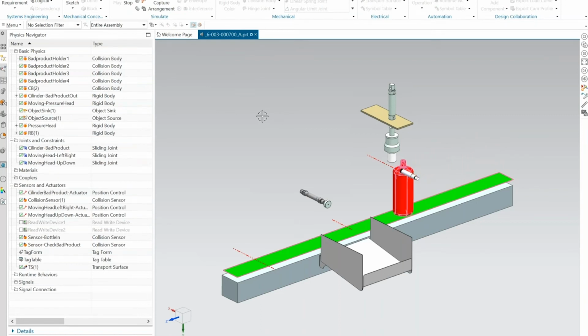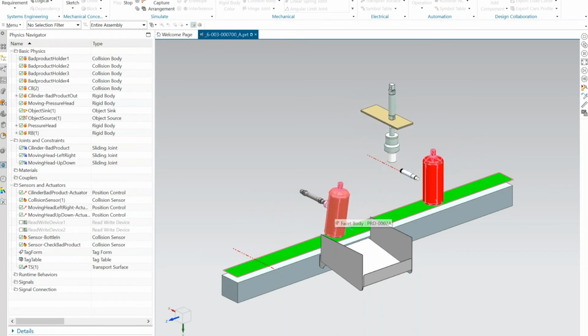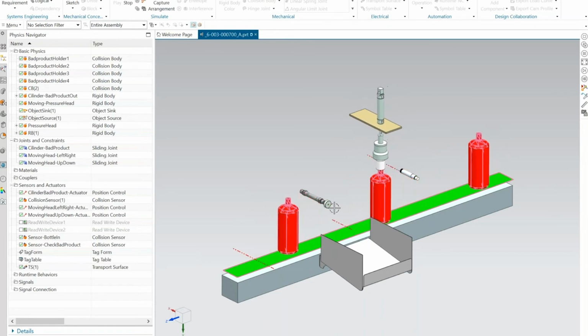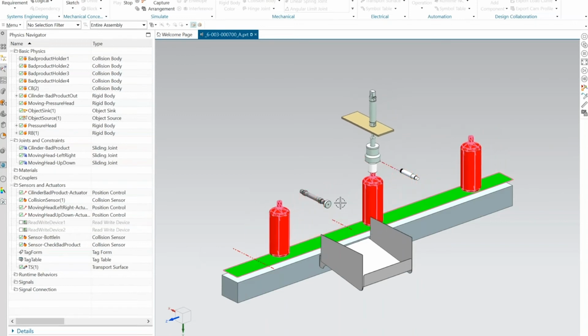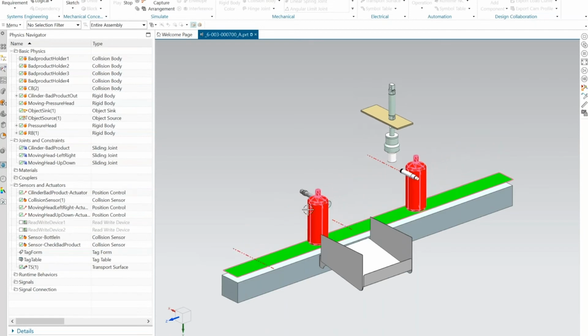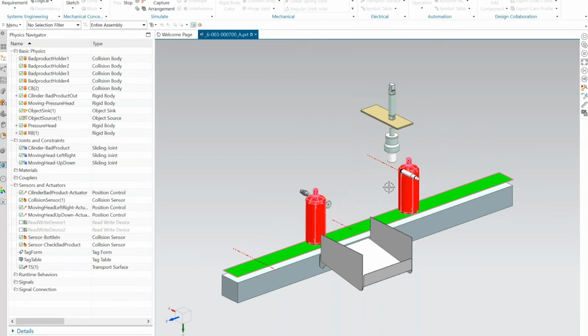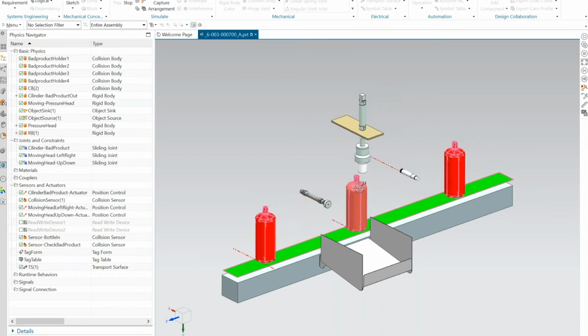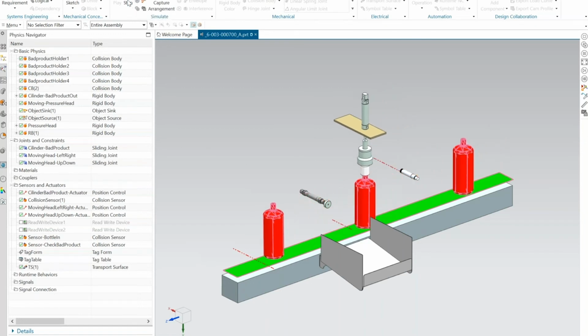And just this easily, we're able to add those physical properties. Uh-oh, did you notice that? Let's see how that works. Good, I got rid of it. So we found a little bit of an error here, and that is that plunger is just a little bit too far forward. It's nice to be able to see that right now instead of when the machine is being built. And what's cool is you'll notice not every bottle is hitting it, because if you think about the physical properties on there, it would change. So let's go ahead and hit stop.